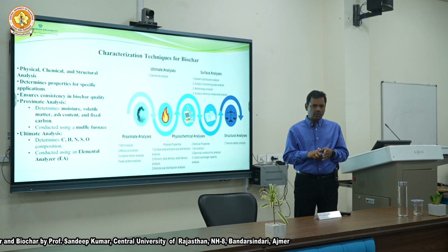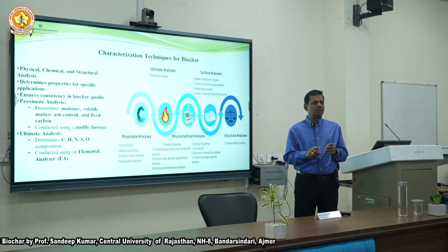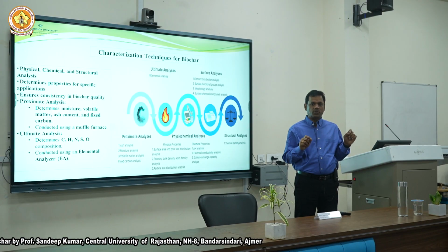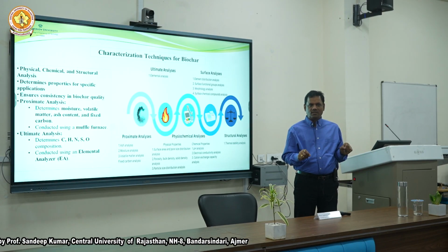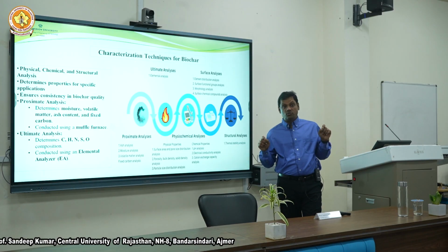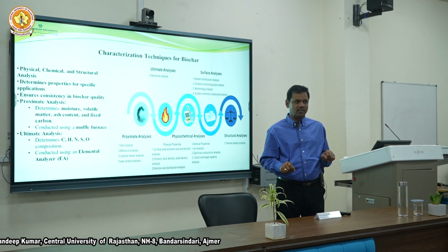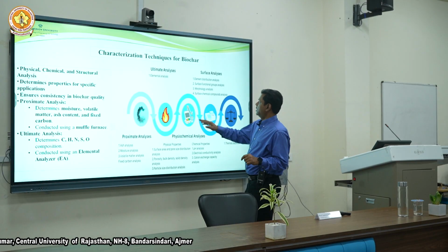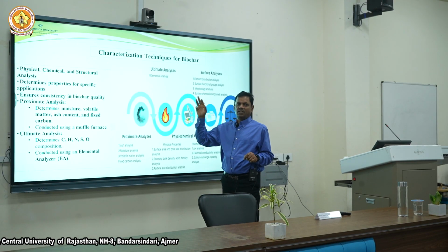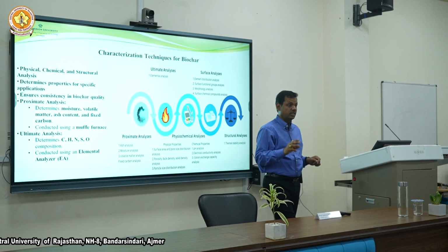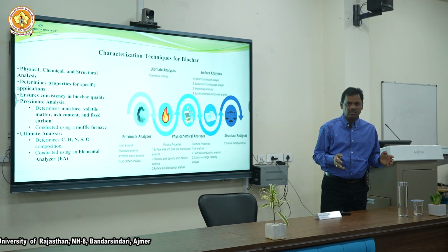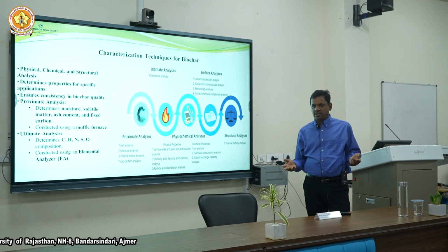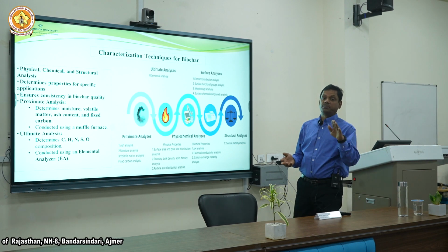So whether biochar or hydrochar, a good way to start is proximate analysis. Remember, it's a carbon business, you need to know ultimate analysis, how much carbon it has. So proximate analysis and ultimate analysis will characterize your biochar very basically, how much carbon it has and how much volatile it has, how it will behave in temperature.